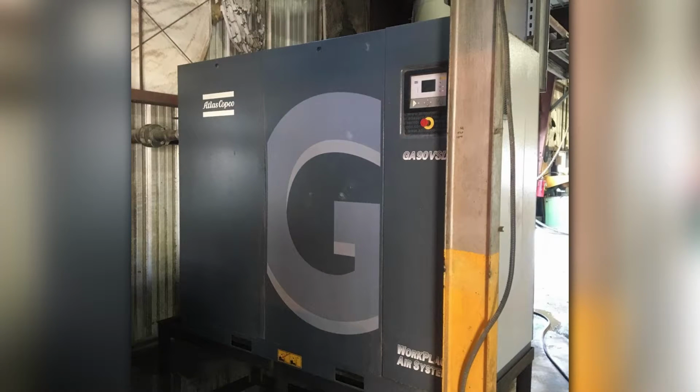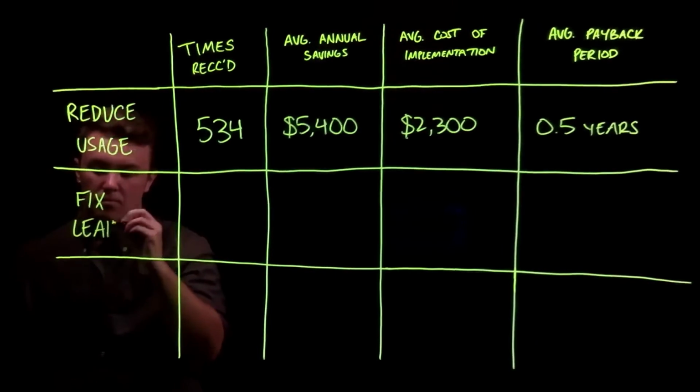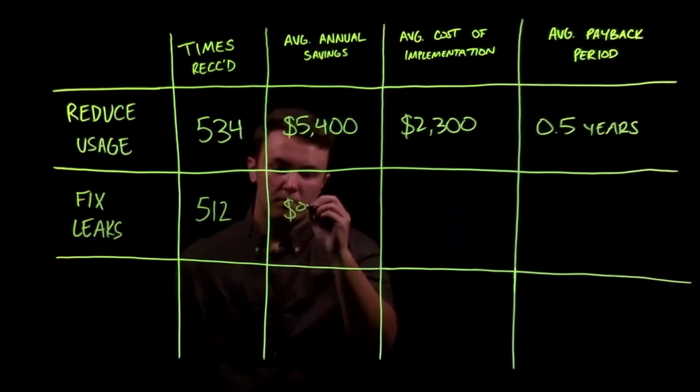It's suggested to walk through your facility and identify all compressed air uses. If possible, also list the flow and pressure requirements for each use. When inappropriate uses are identified, consult with a compressed air system specialist to find other equipment that could be more appropriate and energy efficient.